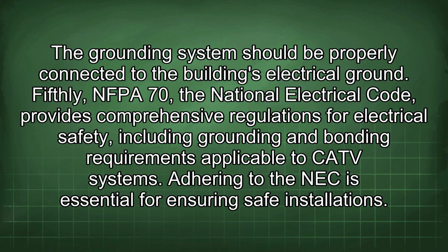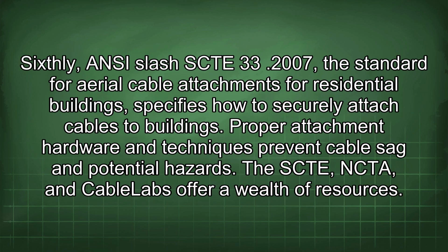Fifthly, in NFPA 70, the National Electrical Code provides comprehensive regulations for electrical safety, including grounding and bonding requirements applicable to CATV systems. Adhering to the NEC is essential for ensuring safe installations. Sixthly, ANSI/SCTE 33, 2007, the standard for aerial cable attachments for residential buildings, specifies how to securely attach cables to buildings.